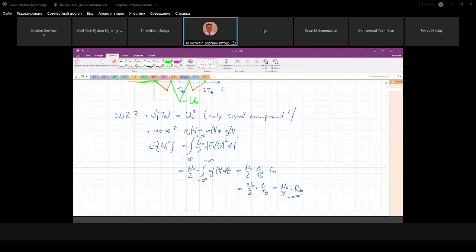Why do we only look at the right-hand side? Because in the real world, you measure this, and it's a technical noise power spectral density, so only a right-sided spectrum. For instance, I gave you this example, N naught is the Boltzmann constant times absolute temperature. This is not the system theoretic power spectral density. This is the real-world power spectral density.